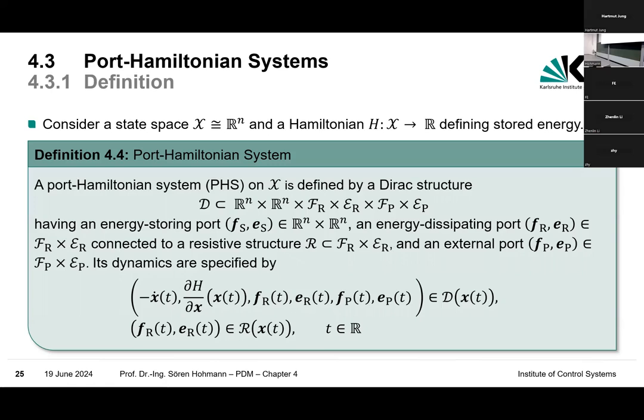One are Kirchhoff's laws, and second, these resistive equations, which are direct relations which couple some of the variables we introduced. And then you have these differential equations for the inductances and capacitors, and then everything is collected.